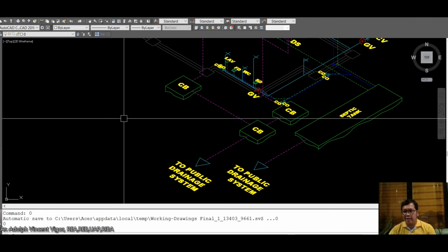Just by looking at this, you won't get this 100%. That's why you must try to practice and implement. So the key here, class, when you're drafting plans, especially using manual, is practice, and make sure that the line weights that you are using are distinguishable and understandable.